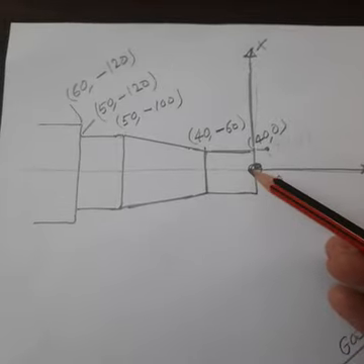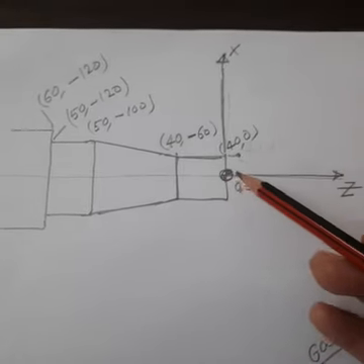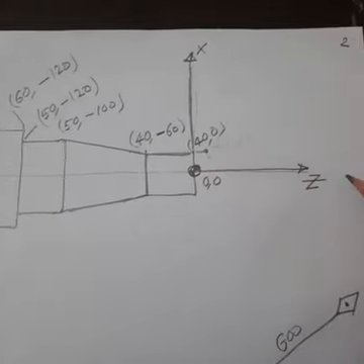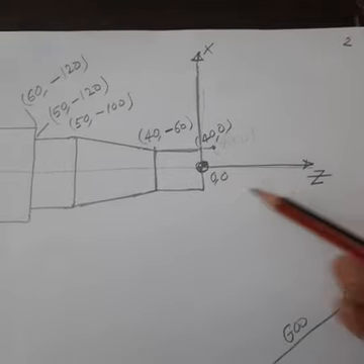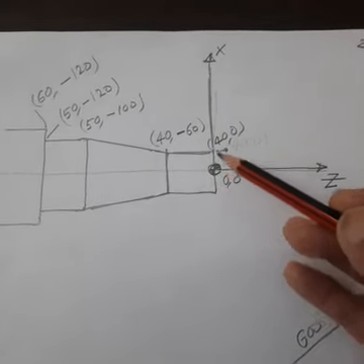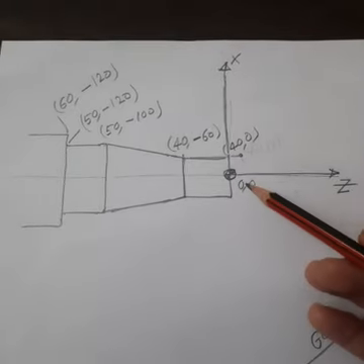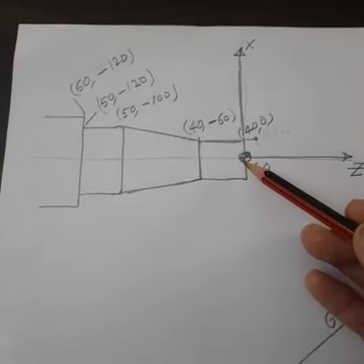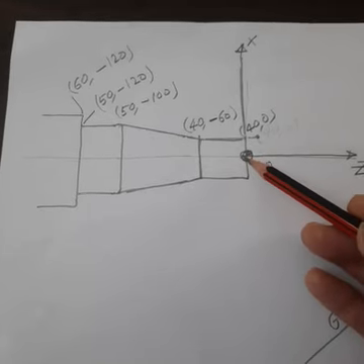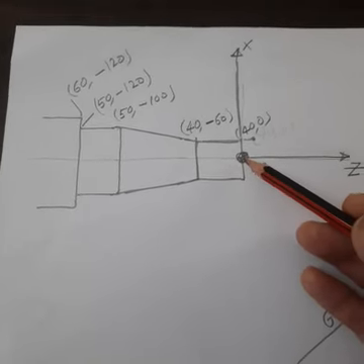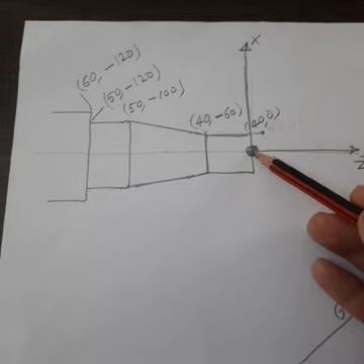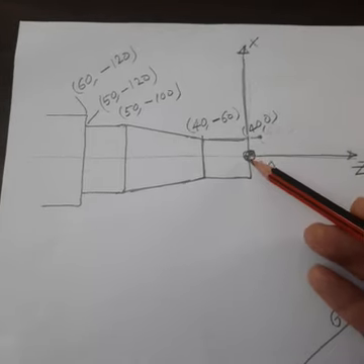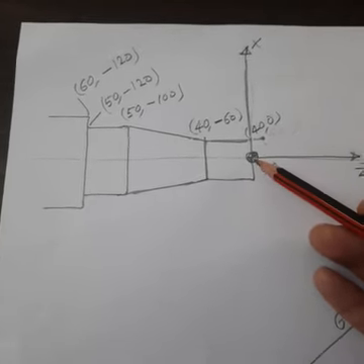So when you take this as the origin, towards the right side is the positive z direction, and towards this direction is the positive x direction. So normally it is better to consider the right end face axis as the origin for the workpiece coordinate system.